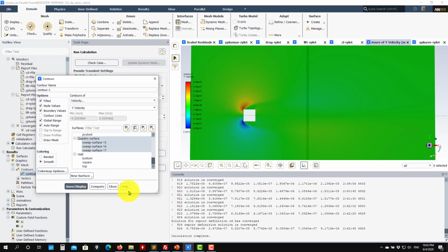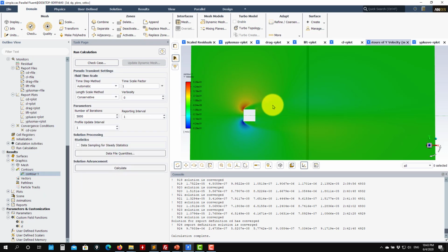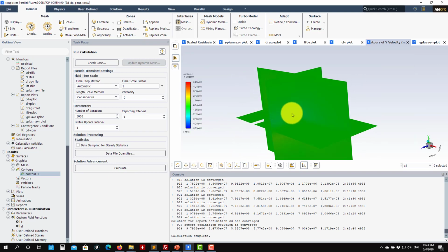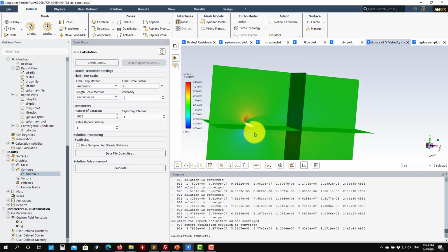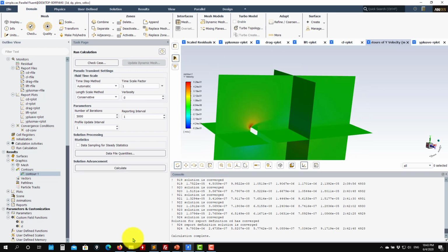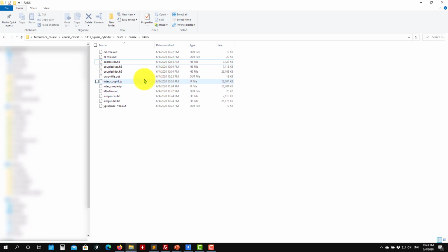So this is why it's always a good idea to run coupled and then SIMPLE. Coupled, you reach fast some steady solution, then switch to the SIMPLE to see if you can capture some oscillation, if it can trigger some oscillations. So we have the two solutions. We save the two files, okay, the two interpolations that we're going to use now in a final mesh.